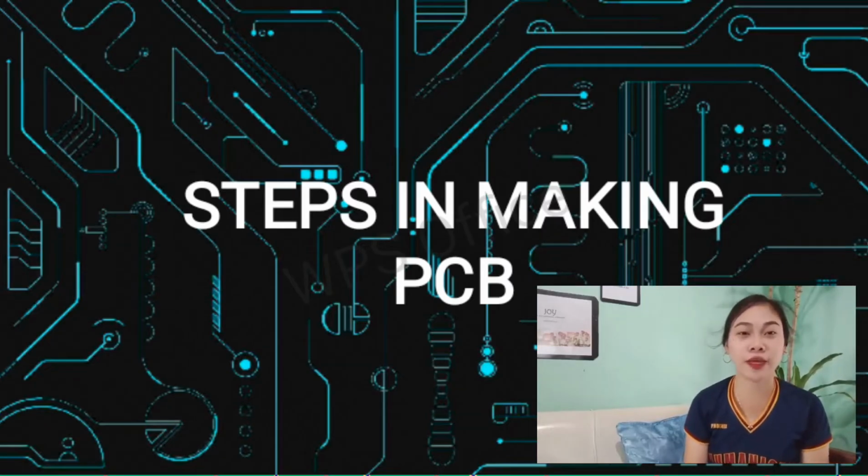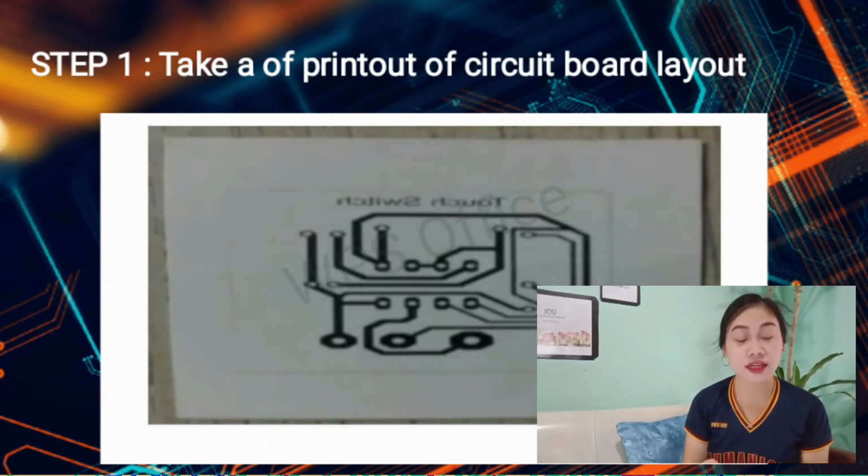Proceed to the steps of making a PCB. Step 1 is to take a printout of the circuit board layout. Print your PCB layout using a laser printer and A4 glossy photo paper. Keep in mind the following points. First, you should take the mirror printout. Second, select the output in black, both in the PCB design software and the printer driver setting. And third, make sure that the printout is made on the glossy side of the paper.